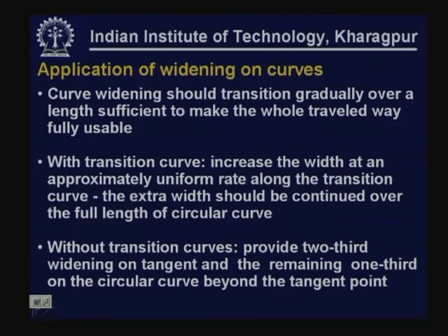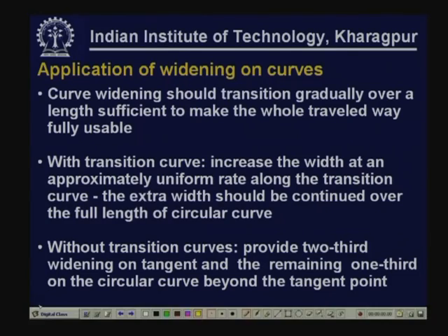Curve widening should transition gradually over a length sufficient to make the whole travelled way usable. That means it should be introduced gradually in such a manner that the whole travelled way becomes usable. This is one consideration. The whole travelled way should be made usable. That means the driver behavior, or the path of driving, should be recognized and considered in